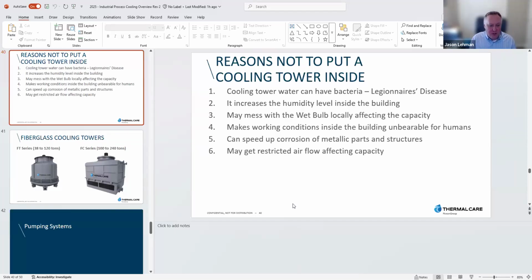The last thing you want to do is have your temperature all of a sudden drop rapidly or say it rises rapidly, compressor runs 100%, and then the temperature coming in drops rapidly. And now the compressor's running 100%, it drives the temperature of the fluid down, cycles off, and then it comes back up again, but now your compressor's in an anti-cycle state.